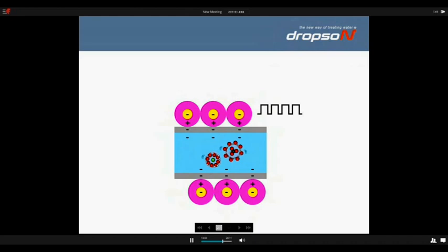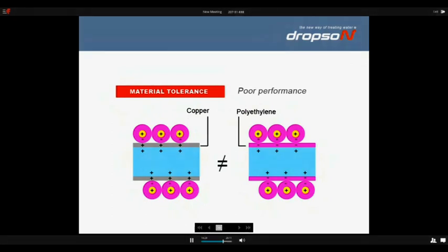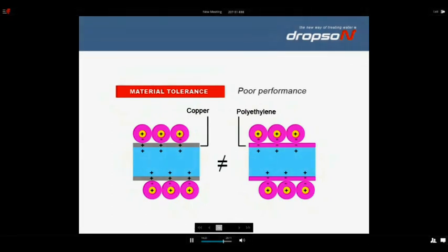If we send an alternate tension to the wires, positive, negative, etc., the water molecules will be sometimes attracted and sometimes repelled. Therefore, the solvation spheres will be weakened and broken down to create non-encrusting microcrystals. The main inconvenience of these systems is that they have been designed to be installed on existing installations. The wires can wrap around copper, PVC, polyethylene, etc.